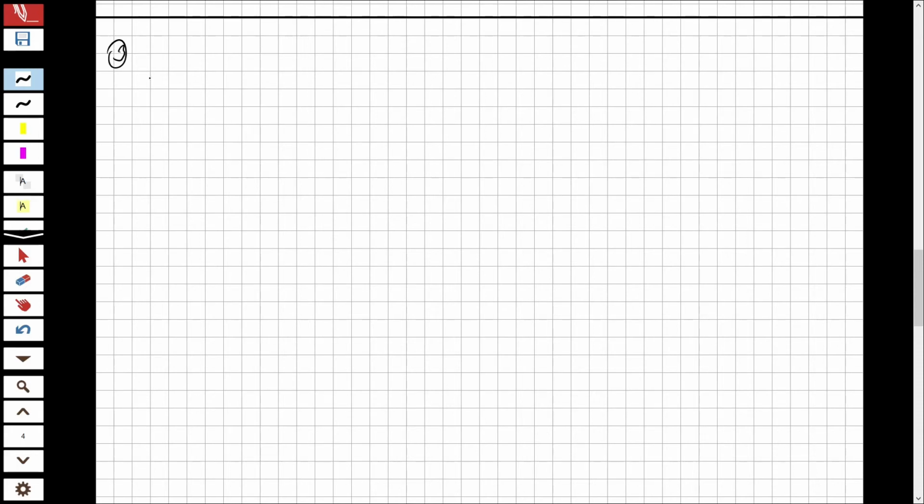So let's write it. Rho equal to AS over bw multiplied by d. What is AS? The bottom steel, 1520 over 300 multiplied by 480. This will be equal to 0.01055. So let's write here rho prime. Rho prime is equal to AS prime over bw multiplied with d.